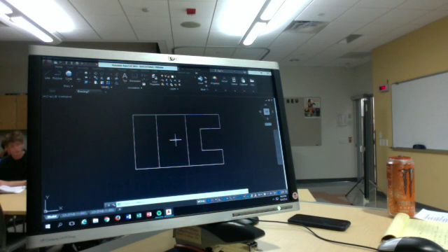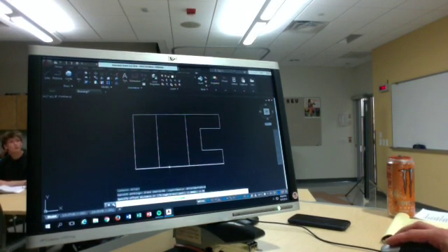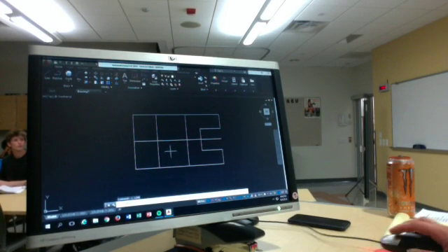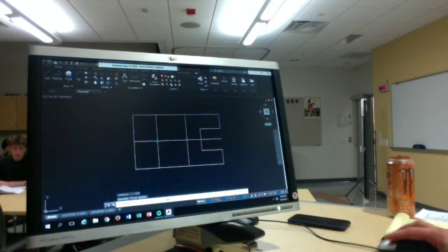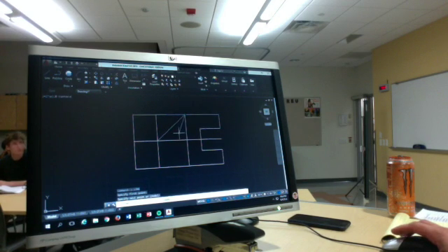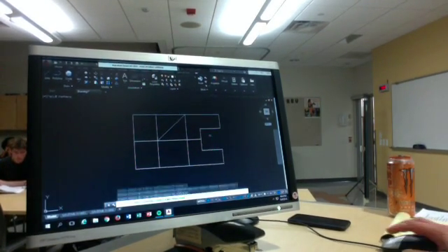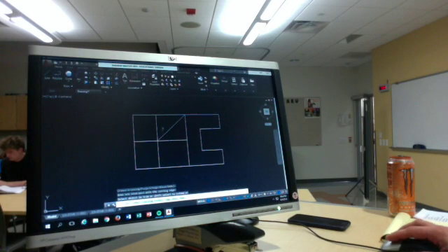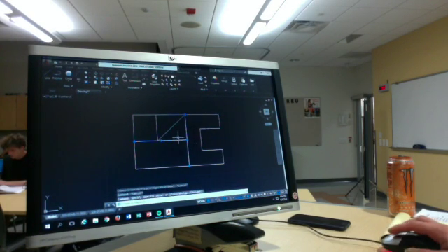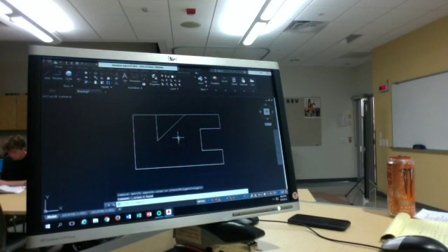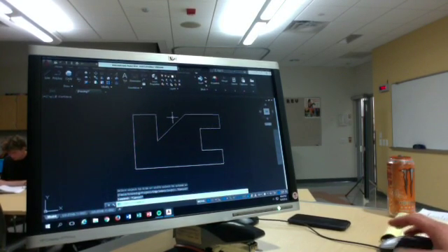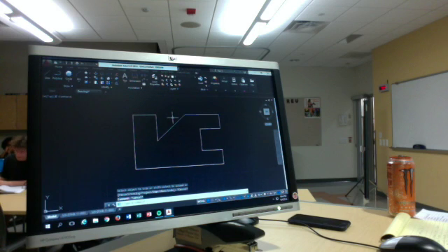Wait. Yeah, that's not going to be 45 degrees. So we're going to offset a line up from the bottom. So offset 1.75 up from the bottom. Now we can actually draw the line at the correct angle, because the line starts here on this point and it goes up to here. Okay, it is 45 degrees, but still. Then we'll just want to trim everything away that we don't need. That line we're going to delete. We can delete these 2 lines. And the last thing that we're going to trim is that. So there we go. We've already created that one.